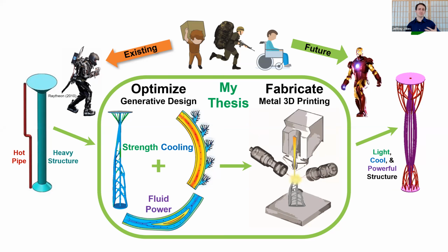Generative design is a big buzzword these days, and the basic idea is that it takes all the iterative guesswork out of designing a product that is then optimized for whatever task needs to be performed. First, you define environmental forces, temperatures, or flow rates, and then important goals like reducing weight or temperature. Then you click run and watch as the product evolves into being by adding, subtracting, and moving material, guided by lowering the stresses, temperatures, or pressures until it reaches a minimum shown in blue.